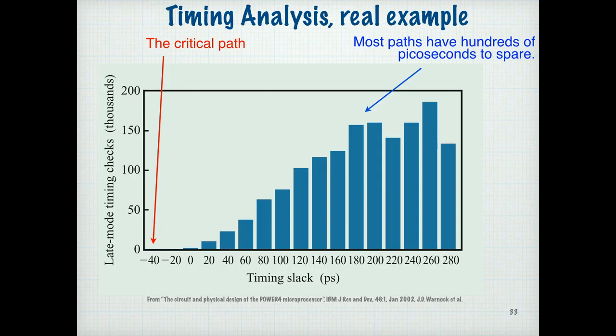So that's bad. So at this point in the design process, the design isn't running at the speed that it should be. So the designer will go and focus on this path, change the circuit somehow. Right? For you, it would mean probably change your Verilog, maybe put a register, cut that combinational logic into 2 pieces, put a register if you can, add a pipeline stage, move some registers around. I'll show you how to move registers around a little later. Right? And then fix that path. And then the next one will be the critical path. And you kind of keep fixing one at a time until you get to the point where they all meet timing.